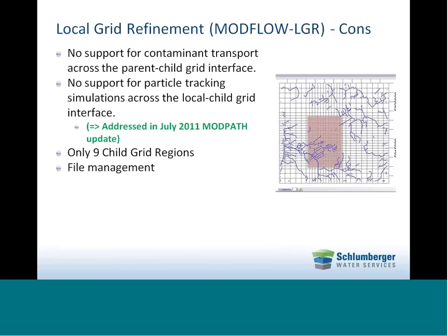As mentioned in the previous slide, you can have up to 9 child grids, so I kind of consider that a pro and a con. It's really designed if you want to have just a few areas of refinement, but MODFLOW LGR certainly isn't designed if you want to do refinement around all your wells or all your flow boundaries, for example.